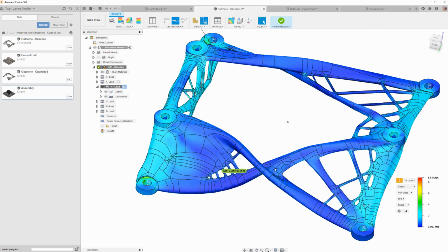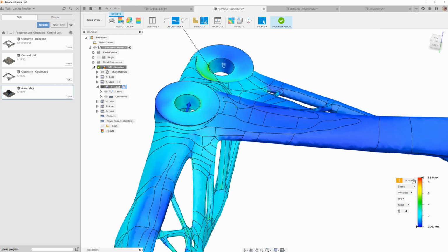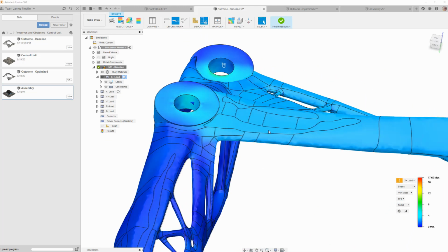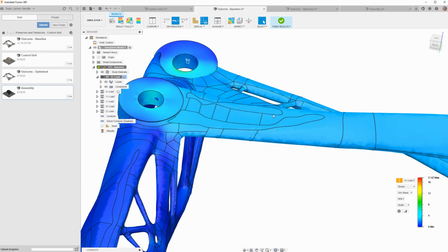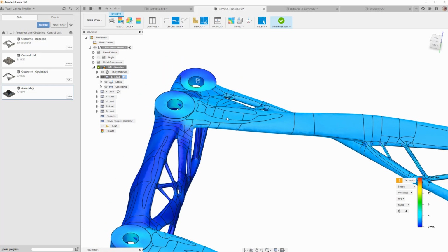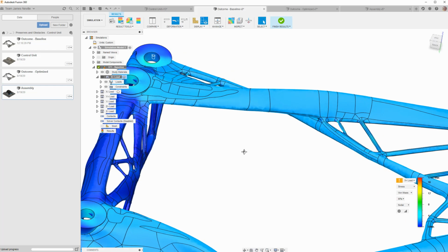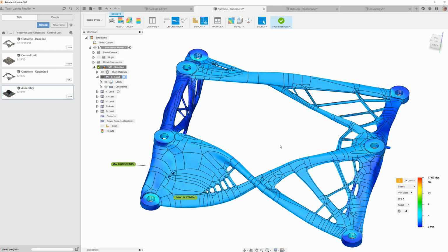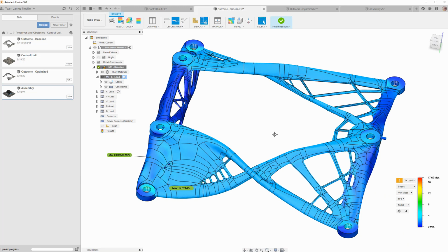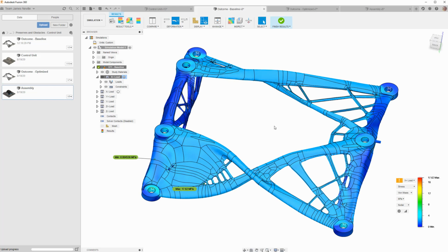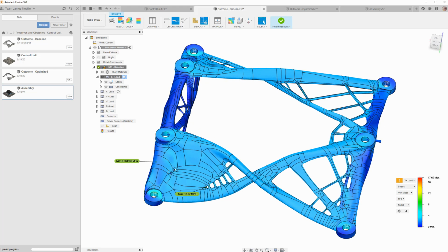I don't see too much of an issue on the top. I actually don't see any stress concentration at all with any of the load cases in this cut. You can see this sort of lake-looking shape here. That's the remnants of the assembly cut there. I don't see any stress there, but this control unit, when mounted on this bracket, if there's any vibration, whatever, this is actually going to touch here too. And is it going to be a big deal? Maybe not in this case, but for some models, absolutely, that could be a source of additional load, or maybe sometimes in contact transient or vibration load. So typically things that we want to try to avoid.